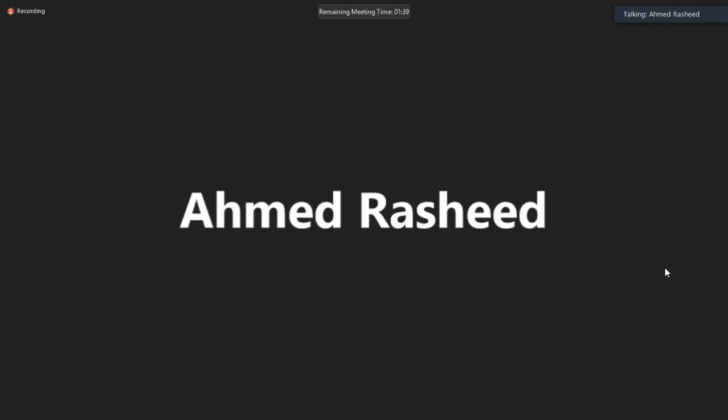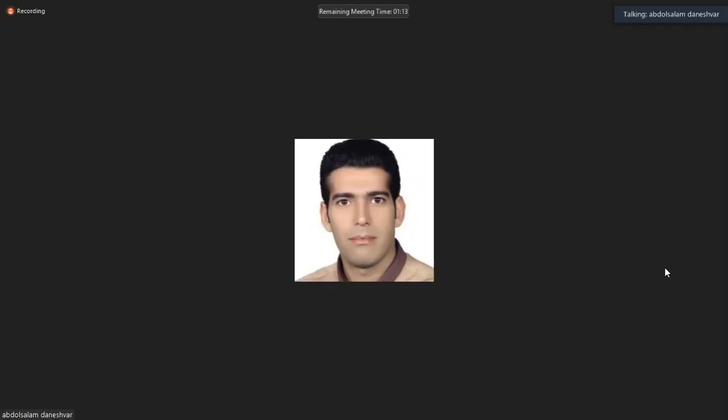And currently, for example, Schlumberger has very developed LWD tools like MicroScope. You can even image all your formation through your LWD tools. But even though, you have to do wireline logging before you run your completion. I want to know how much you trust this data in the moment you are drilling and working on the reservoir formation. How much do you trust the data you got? You know what I mean?